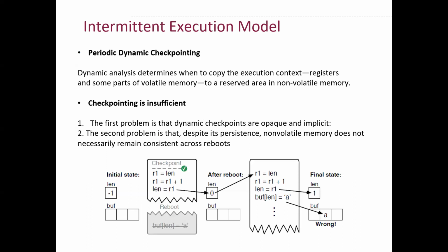Dynamic analysis determines when to copy the execution context, like the registers and your volatile memory, to a reserved area in non-volatile memory. There are many different ways to do this, maybe using a timer or using an ADC to measure your input voltage. These are just some basic examples.